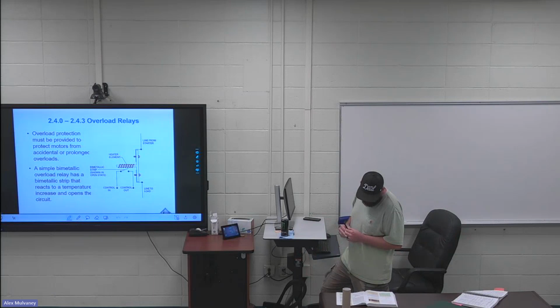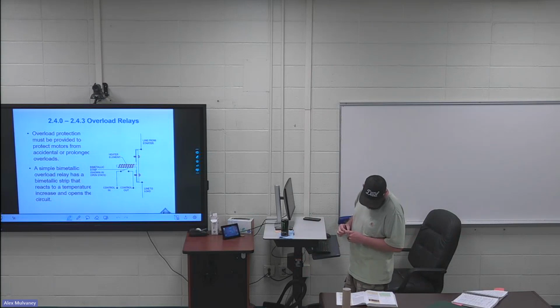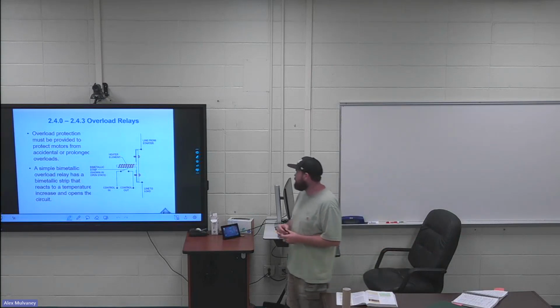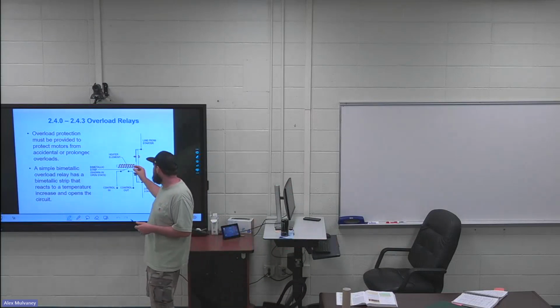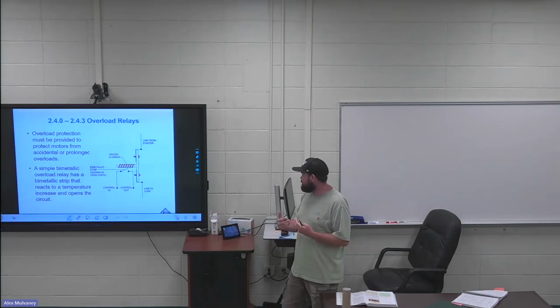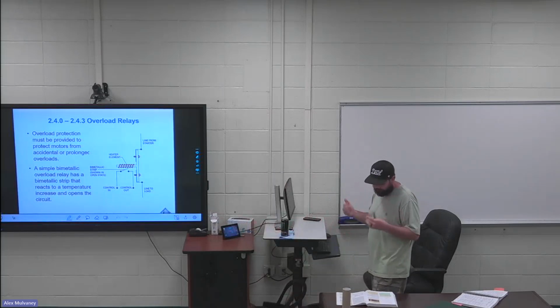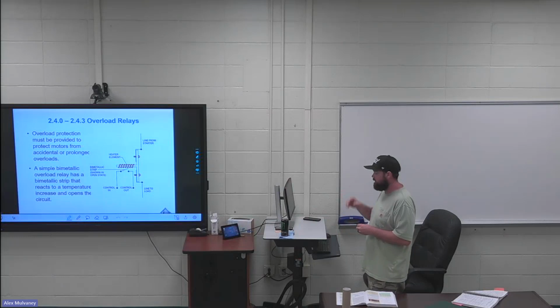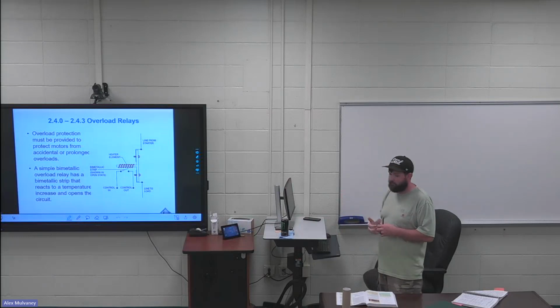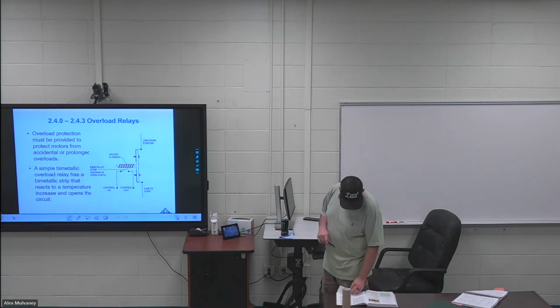The ideal overload protection for a motor is an element with current sensing properties that are very similar to the heating curve of the motor. It protects and will open the motor when the full load current is exceeded. So what they're saying is this heater element acts the same as the internals of that motor. Whenever too much current is being pushed through that, it'll open up, so it acts like the motor, and it knows when too much current is flowing through it.